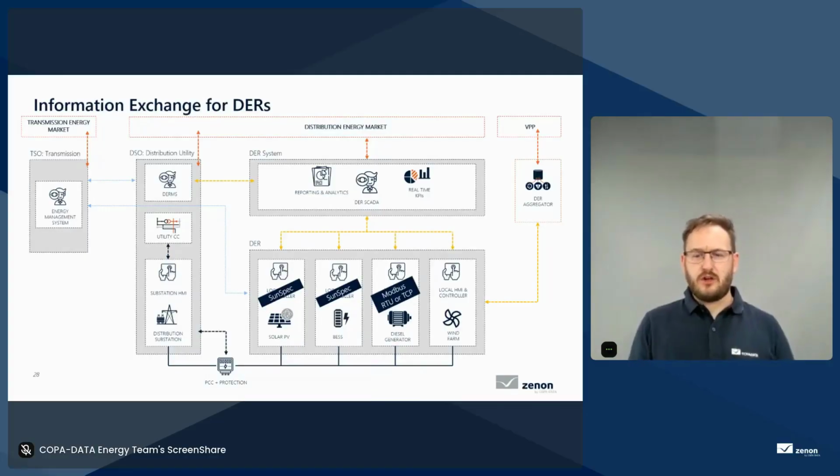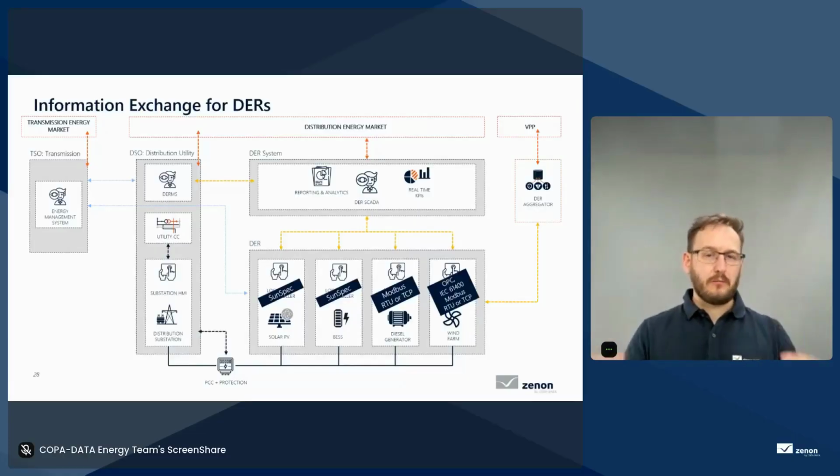When it comes to diesel generators or gas generators, for that matter, a wide array of protocols are normally supported, but more often than not, you will also find classic protocols such as Modbus RTU or TCP-based Modbus. When it comes to wind farms, here we see OPC, IEC 61400 data models, and again, Modbus. So all of these can be connected to with Zenon, the data retrieved, and also set points sent down from the DER system to control the DERs as required.